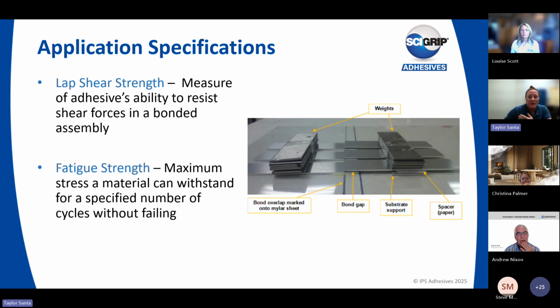So another type of strength that is typically looked at is lap shear strength. Before we really talk about the strength, you have to understand what lap shear bonding really looks like. This configuration of bonding, where parts are bonded in an overlap, like seen here in this photo, expects to see force applied by pulling pieces away from each other instead of pushing towards or bending.